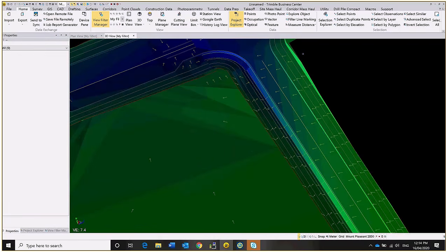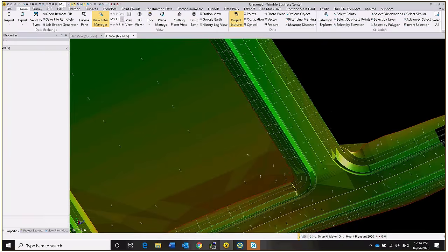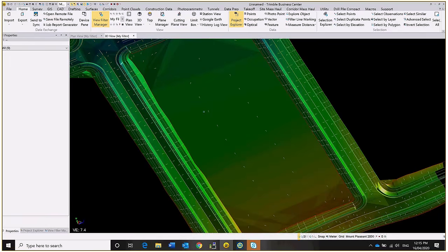And we can click on our surface again. And we've also got one here called transparency. So in transparency, if you have a couple of surfaces and you want to be able to visually see them colliding together but seeing both surfaces, you can turn the transparency up, so we can go 50%.